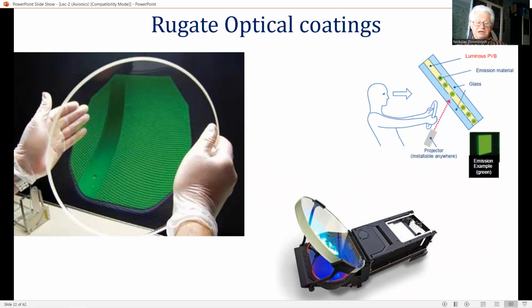A rugate dielectric coating is a multi-layer coating having a sinusoidally varying refractive index with thickness, which can synthesize a very sharply defined narrow wavelength band reflecting coating, typically around 15 nanometers, at the CRT phosphor peak emission. The coating exhibits similar high reflection and transmission values to holographic coating, but is not capable of generating optical power.